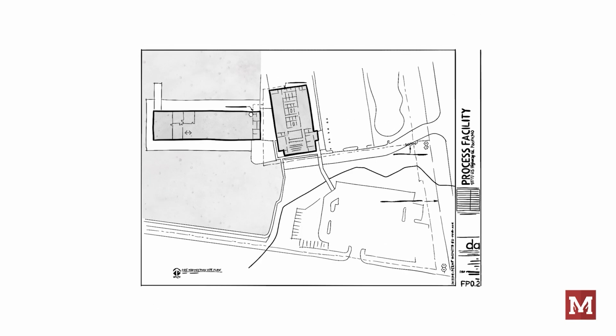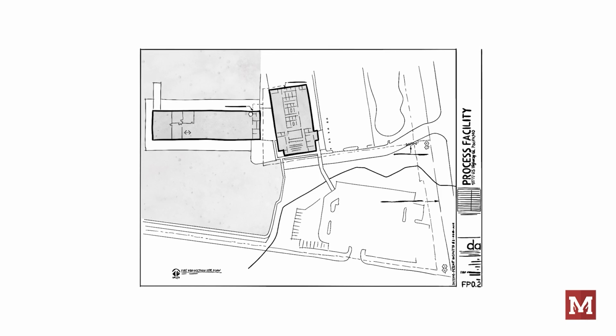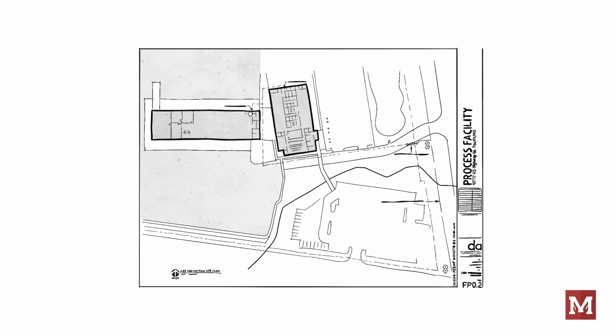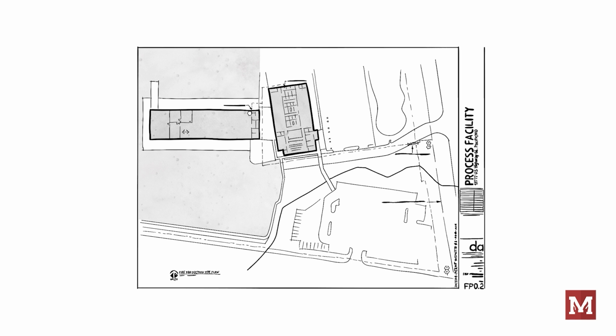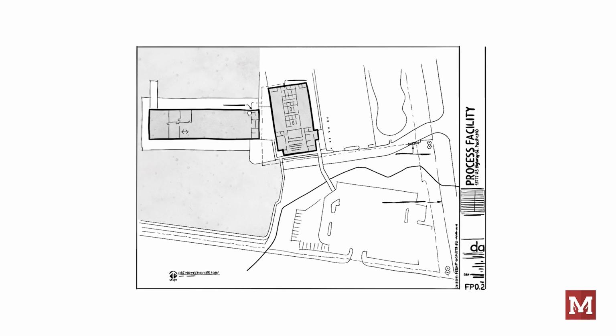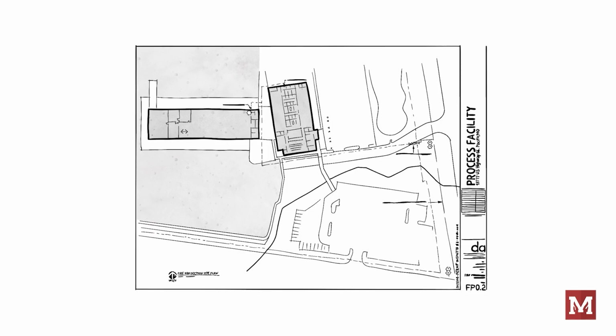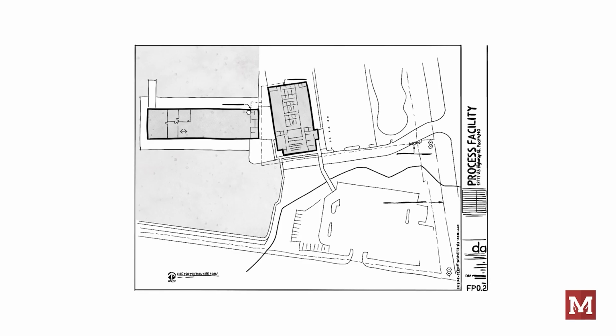The utility drawing is often not included in the set of building plans, but will often be found in the set of civil drawings with the site plan. This is a critical drawing for us to reference because NFPA 13 requires our hydraulic calculations to go from the most hydraulically remote sprinkler back to the point at which the water supply characteristics are known, which is most often the test hydrant from the flow test used as the basis of our design. We have to account for all the pipe between those 2 points, and we can't do that unless we know how the water gets from the test hydrant to our system.